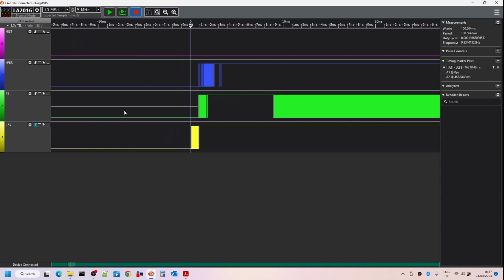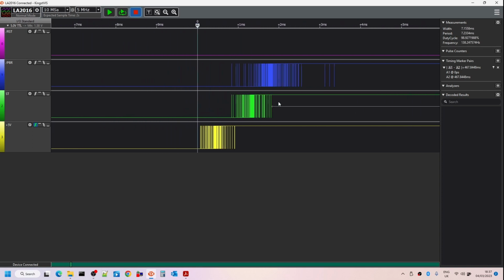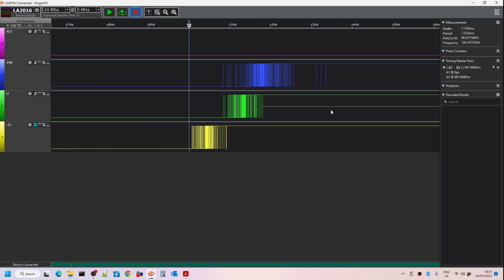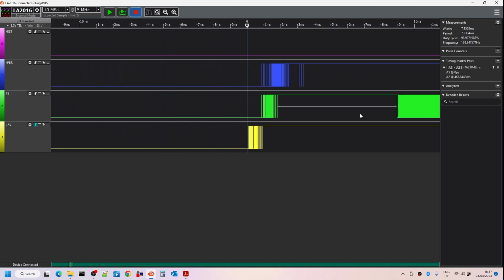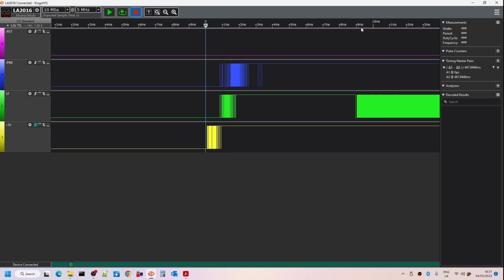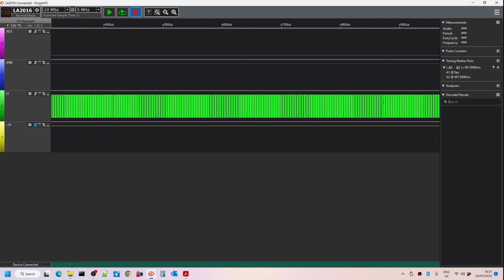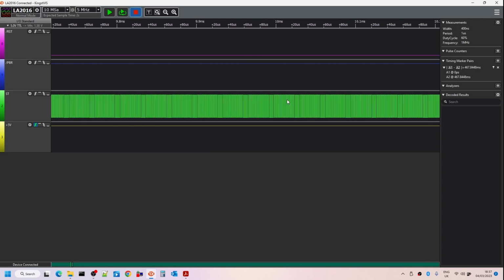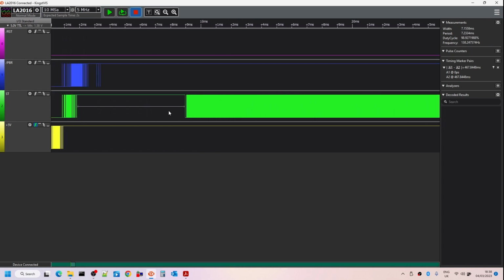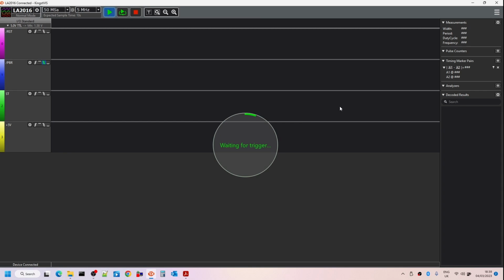We can see here as well that it takes a number of milliseconds for even the clock to settle down. So we can see that it's only until about 10 milliseconds that we actually get a clock signal. So this is one of the E or the Q clock signal lines that we've hooked this up to here. So I'm just going to look at the reset button. We're waiting for the reset button to be pressed, and what I'm going to do is to press it multiple times quite quickly, and then I'll also leave a bit of a gap.